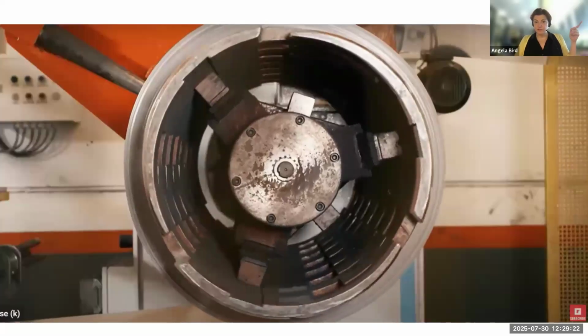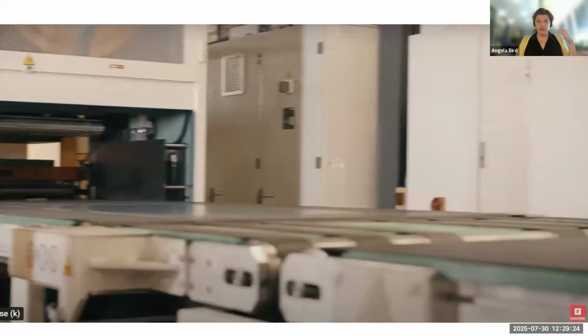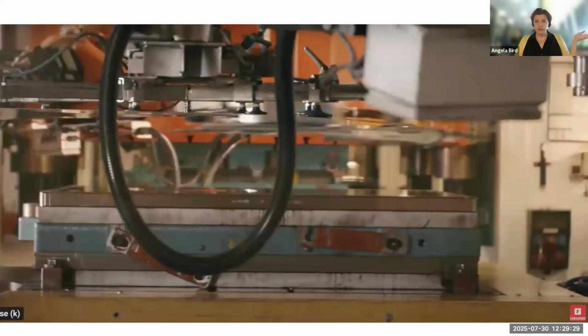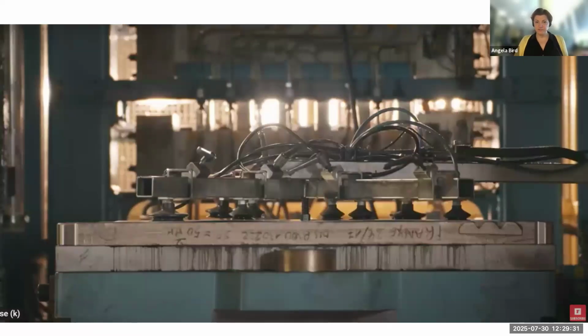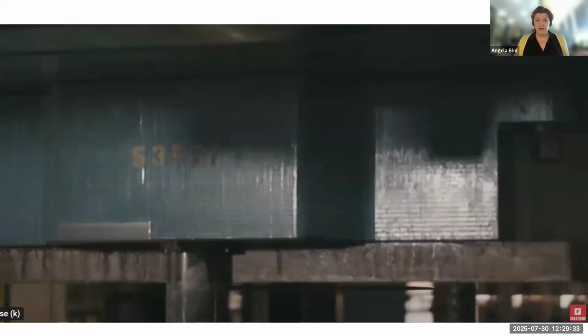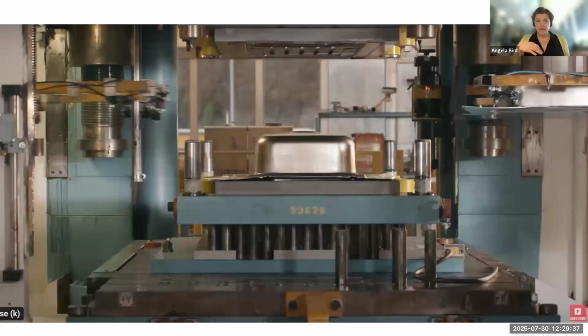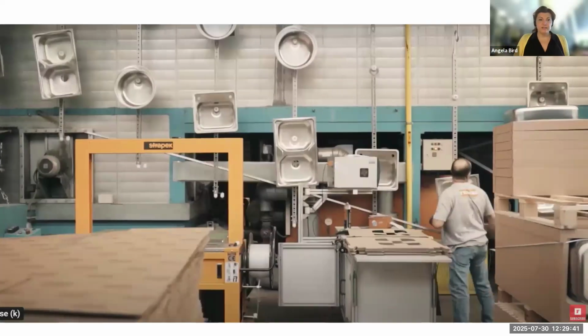So here's a video of the process we just reviewed in the previous slide. You see that coiled up roll of stainless steel. It gets fed through a decoiler. There's the sheet. It's going into that first stage of the press. It gets the first draw, and then it goes through a second draw. And then you can see it's getting put through a washing machine here. The sinks are inspected by a person at every point throughout the process, not just at the end.